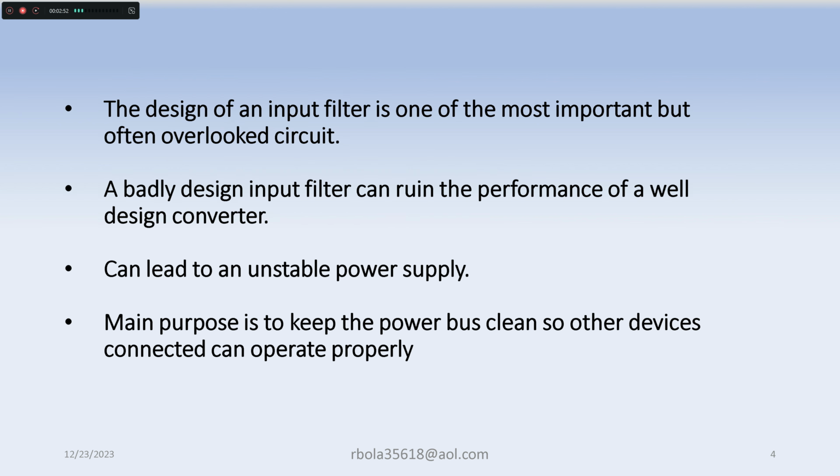Now, when you're designing an input filter, it's an understatement to say that it's a very important part of the power supply. If you neglect it, you can design a good switching power supply, but then if your input filter is not damped or properly designed, you can have a converter that will be unstable in certain conditions.